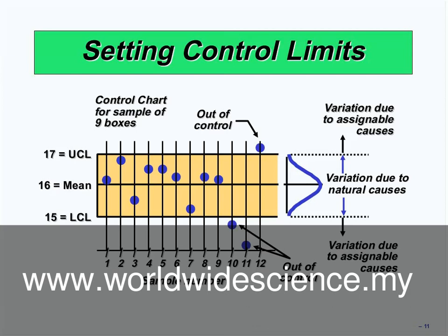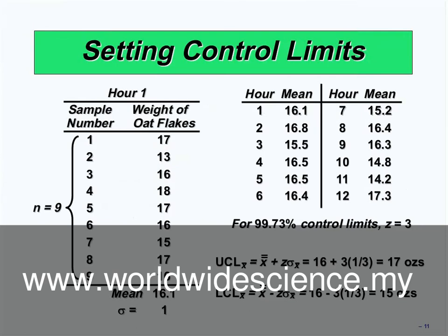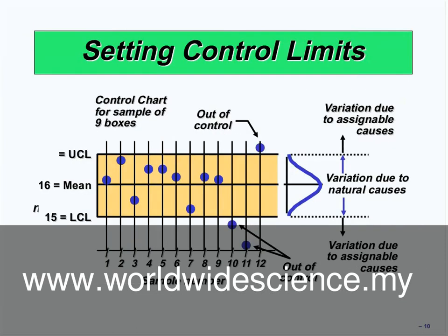After calculating this, the operation manager considers all of the means and checks whether all of the means are between these two numbers, maximum and minimum, or not. If each of the means, each weight, each speed, each length, and every variable that should be calculated is outside of these limitations, the process is not under control.